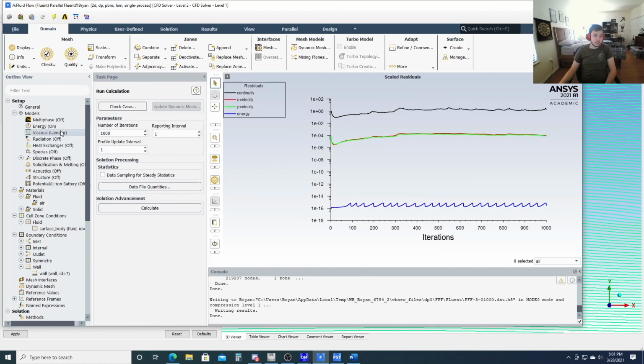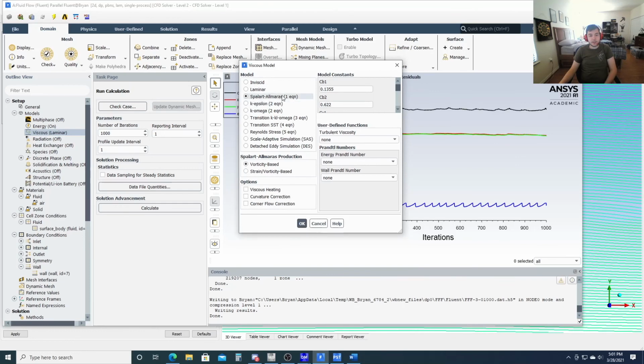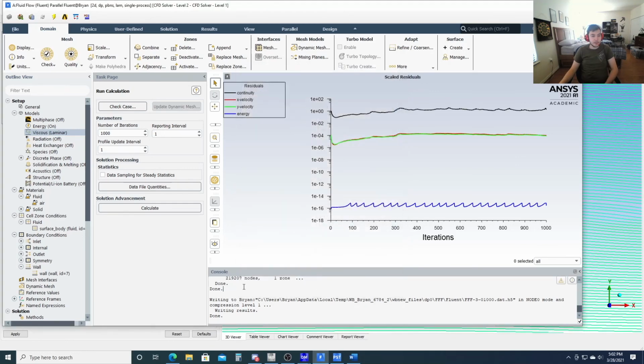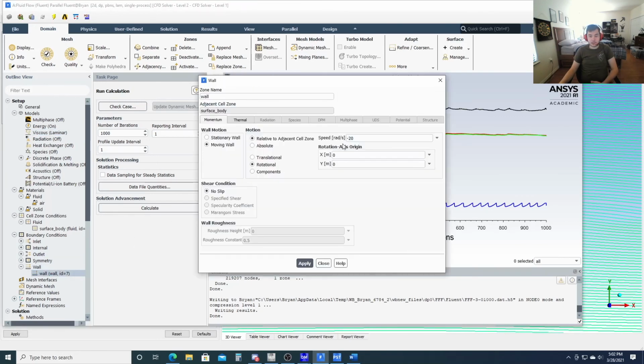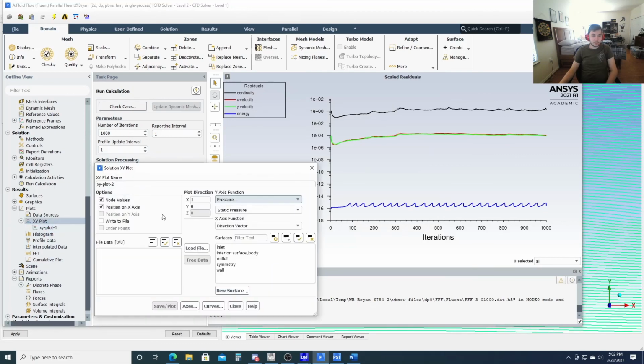And for turbulent, I like to use K epsilon, personally. I've tried the Spalart-Allmaras, and it doesn't work as well, so I just use K epsilon here. And at first I'll put the wall to 0, because that's what I'm supposed to do, put it to -20, put it to -40. And of course along the way, the XY plot, it's the same thing.